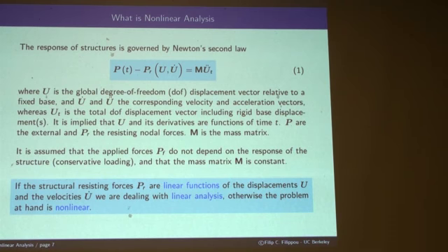So the response of structures is governed by Newton's second law, of course. And you have the applied forces against the resisting forces. The resisting forces are dependent on displacement and velocities. Velocities are strain rates. Displacements are strains. And then we have the inertia term, and under the assumption that the mass is constant, multiplying the total accelerations.